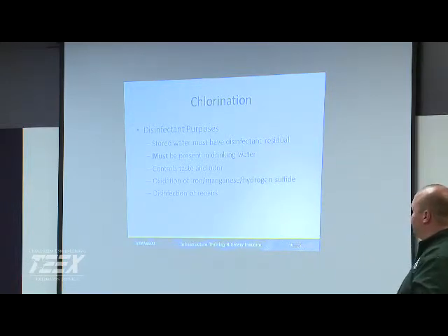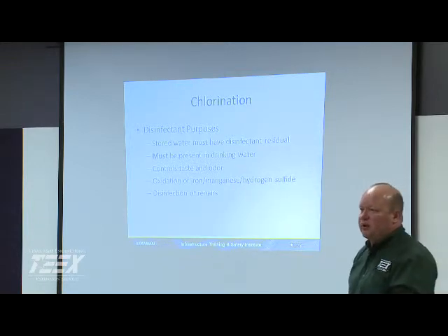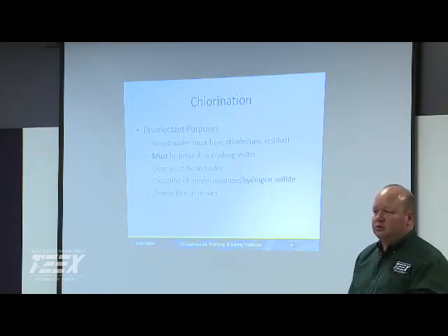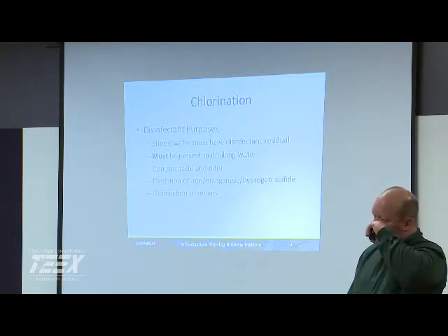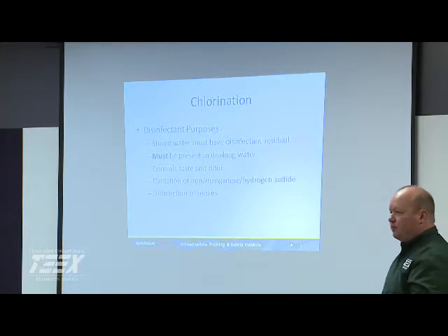We need to make sure we disinfect after repairs. You have calcium hypochlorite that y'all are using. What do you do? Any pipe that we use that's off the field, we swab it with bleach and then put it back in the system and flush it and get a sample. Okay. So you're pulling back tees and residuals and all? Yeah. Every time that we cut it, if we get a negative pressure.